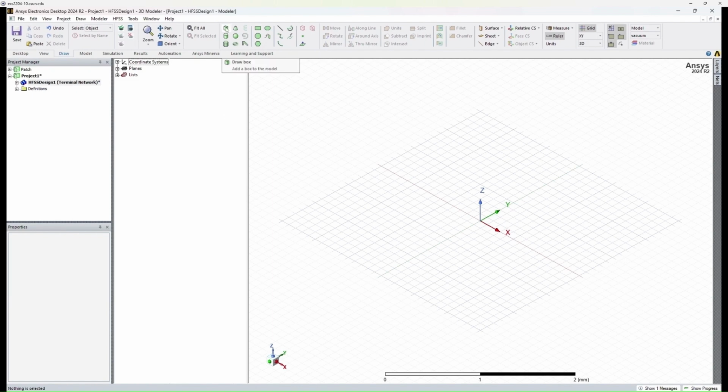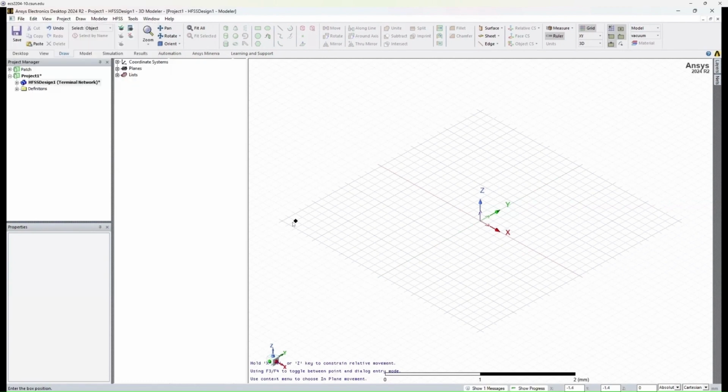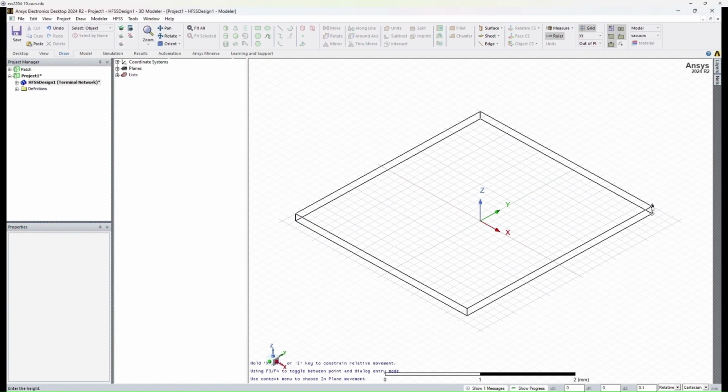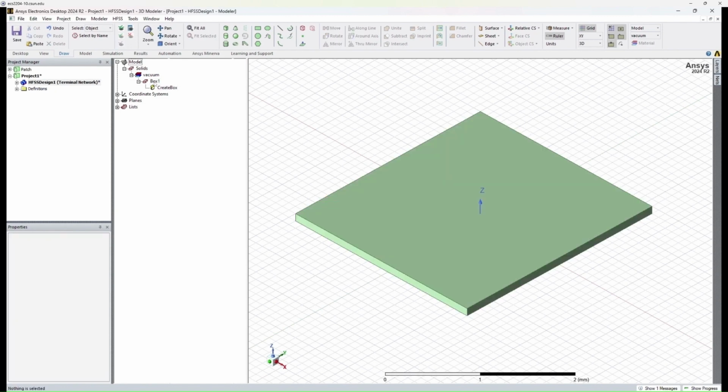So for the substrate, I'll go ahead and draw a box. If you're not in this mode where you have a cursor following you, you can hit F3 and it will change modes for you. Then we can click and drag and just define a simple 3D box with 3 clicks, and then now we're able to dimension it ourselves. So this box is currently much too small. We see it's about a few millimeters wide when we wanted it to be 10 by 10 centimeters.